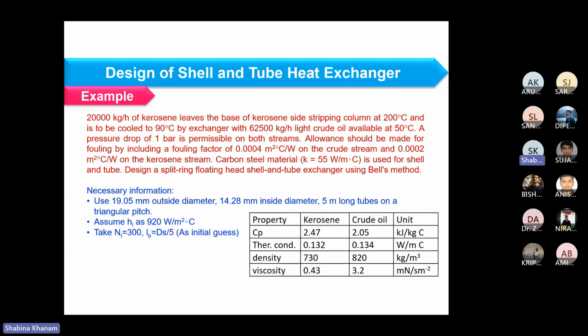When we see the heat transfer coefficient, we have considered the ideal condition first, and then we have considered different correction factors related to other conditions like cross flow, window correction, and we were having bypass as well as leakage. All these we have counted with a respective correction factor. So that is for the heat transfer coefficient.